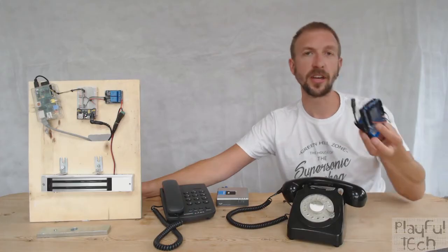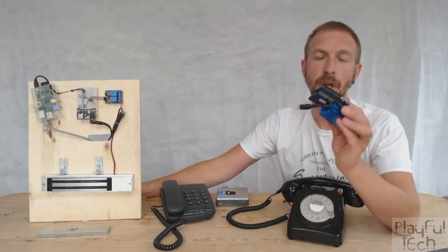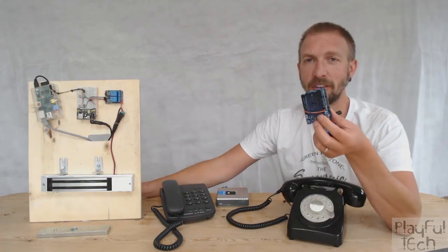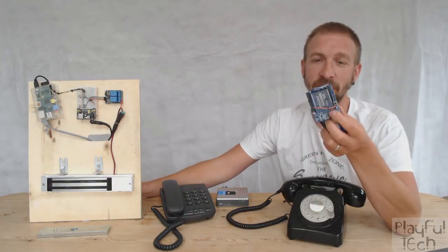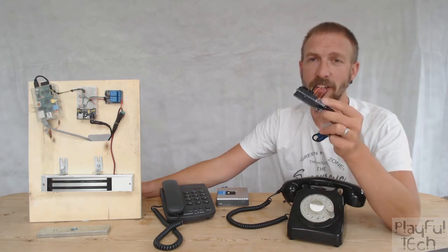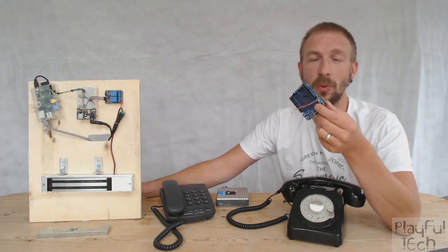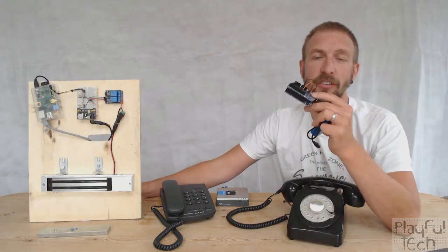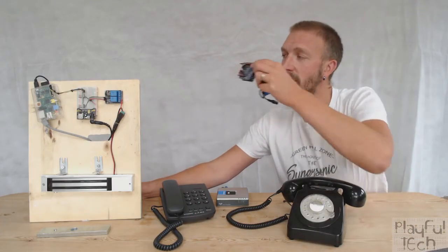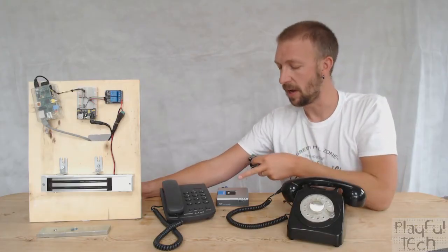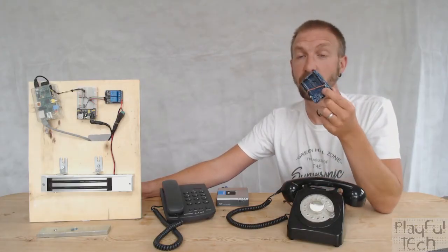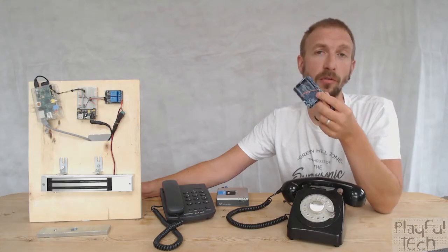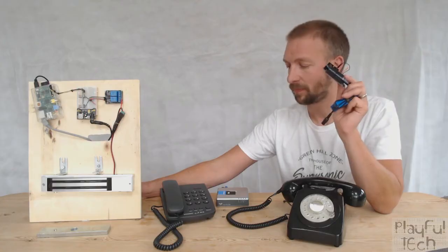The only other thing, like I say, I've got a WeMOS D1. You can also get WeMOS minis, you can get ESP32s, ESP8266s, and you can use basic Arduinos that have either a Wi-Fi shield or an Ethernet shield attached to them as well. You just need something that's going to be able to connect to the same network that these other devices are, and that can run Arduino code, and that's going to trigger incoming or receive outgoing calls as well.